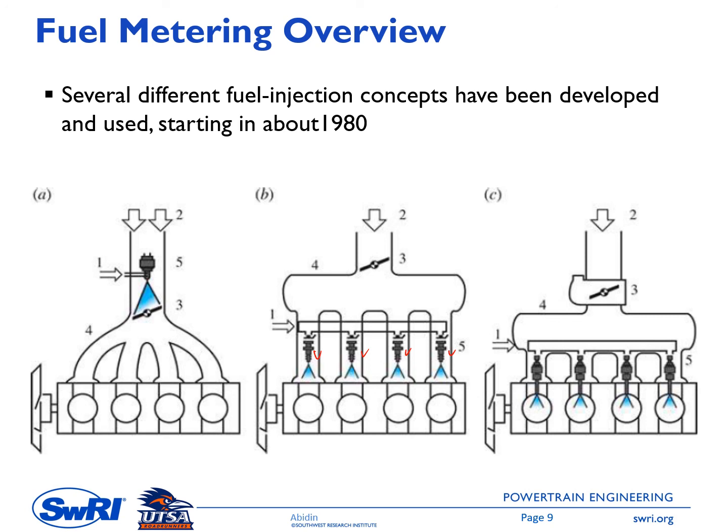The last one is called direct injection. Because this is gasoline, it's called gasoline direct injection, or GDI. Each cylinder has one injector, and the fuel is injected directly inside the cylinder, so it is downstream of the intake valve.